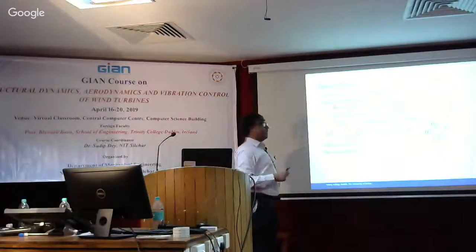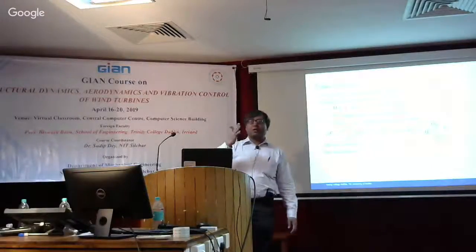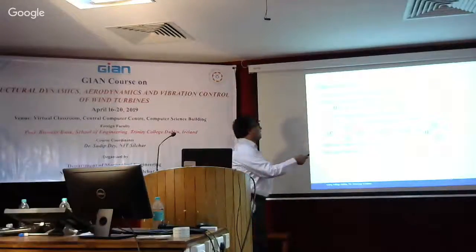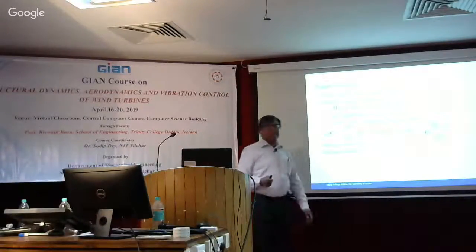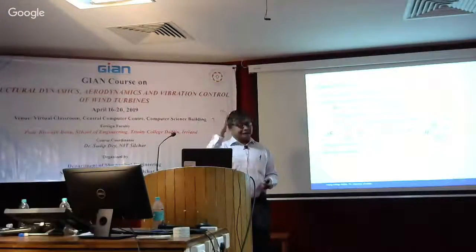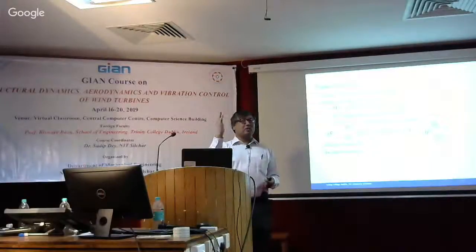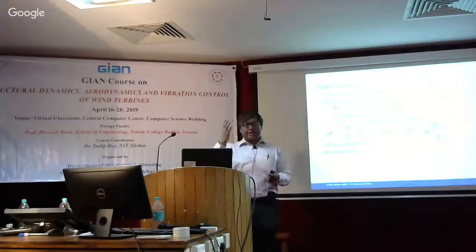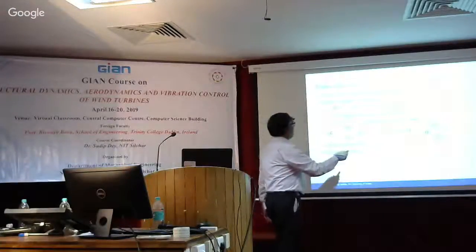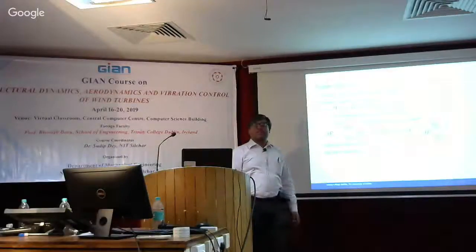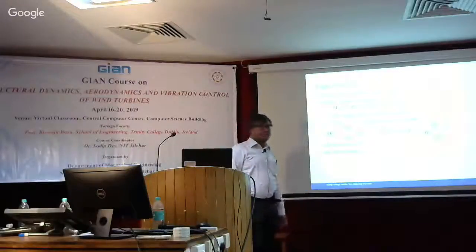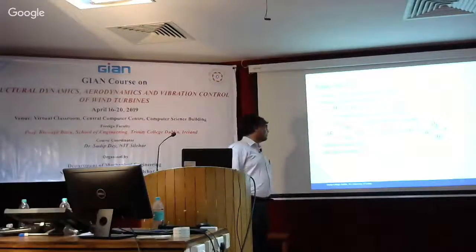So the action of the pitch, obviously I said, is changing the aerodynamic load, right? So then the pitch, when activated, will change the load from F to F plus delta F. Because initially the load was F. If I change the angle of the blade, then the action of that is changing the load acting on the tower. So I've changed the blade angle of the pitch in such a way that the aerodynamic force gets changed from F to F plus delta F. It could be a minus, but algebraically it's plus delta F. It doesn't matter. We'll see what the sign is.